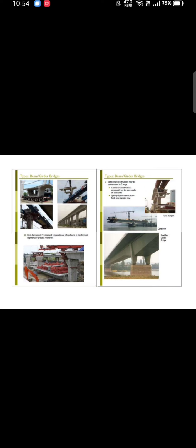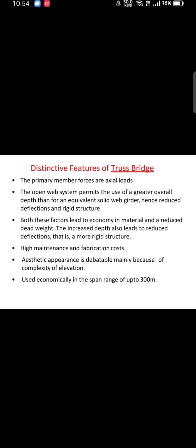The very famous metro rail bridges are all precast bridges only. So they are segmented at some precast yard and then installed. In between them, epoxy glue is laid, and there will be some hollow sections. In those hollow sections, the pipes and tendons will be passed, and the tendons are tensioned and jacked using a hydraulic jack. These perform well in tension as well. So they gain good connection and bonding between all the cells or segments.